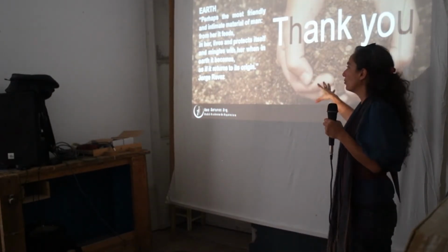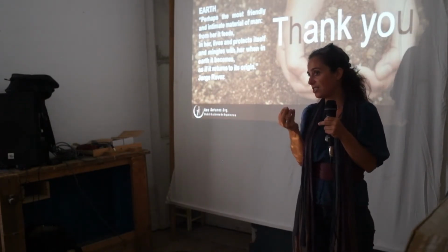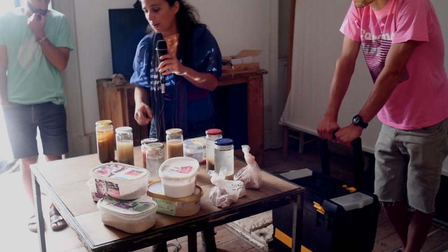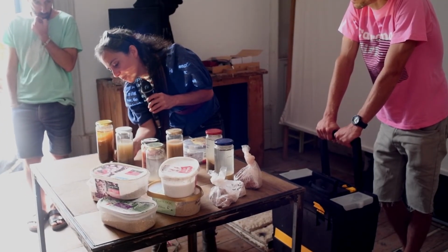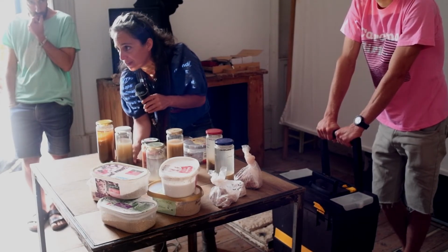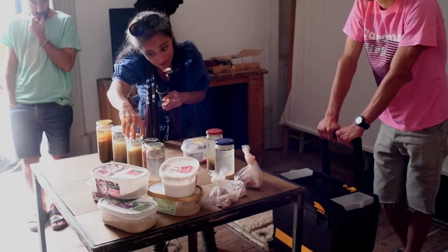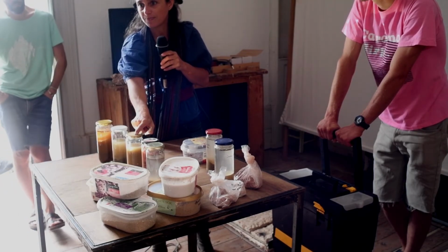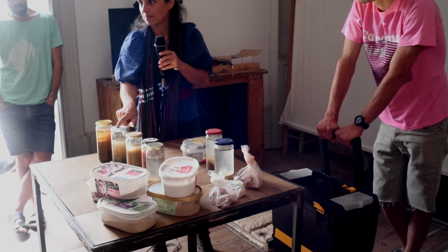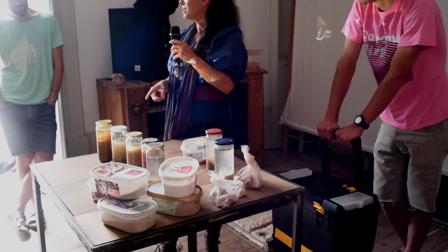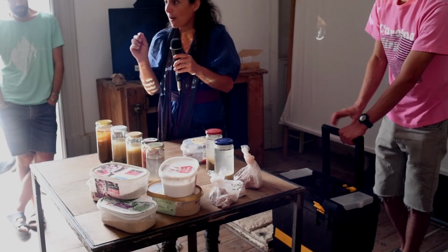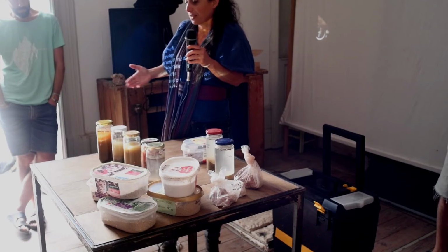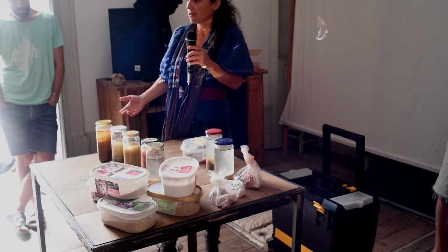So what I do is, I go to the field, I look at the earth, I make my testing in the field. The one that I'm using in my project that I showed you yesterday, the Eco-Ria. So this is sand. I almost have 10%, 15% of clay. It's really interesting. This is from Aveiro. This is the earth that they use for the adobe, and it has less clay than this one. So that's why they use so much lime. They really use a lot of lime, because there's no bonding for the particles, but this is the earth that they have there. This is the only thing that they have to work and build the houses.